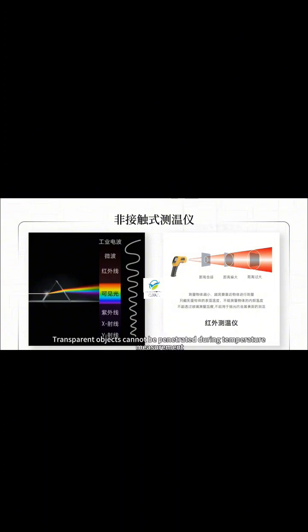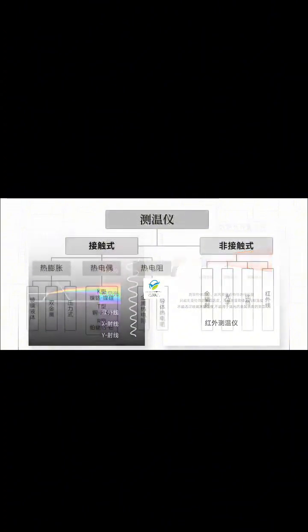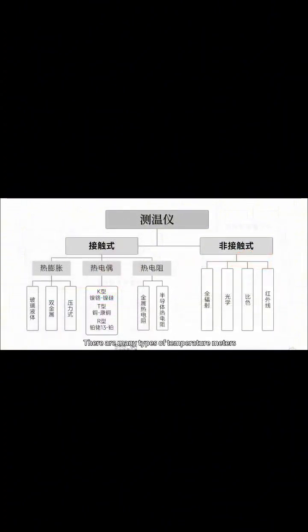Thermoelectromotive force is composed of the contact electromotive force of two conductors and the temperature difference electromotive force of a single conductor. Thermocouples can be selected to use metal wires as required, measuring a wide range of temperatures, from ultra-low temperatures to very high temperatures.